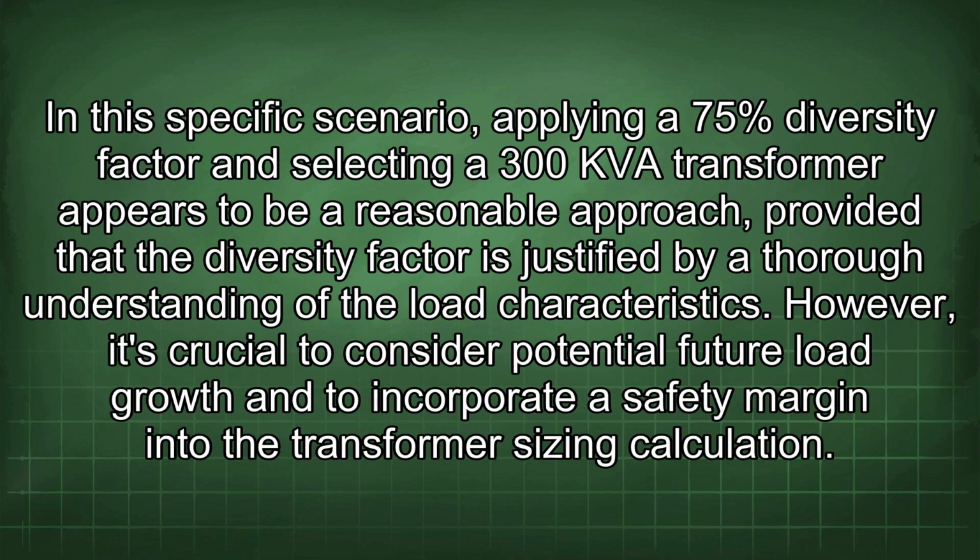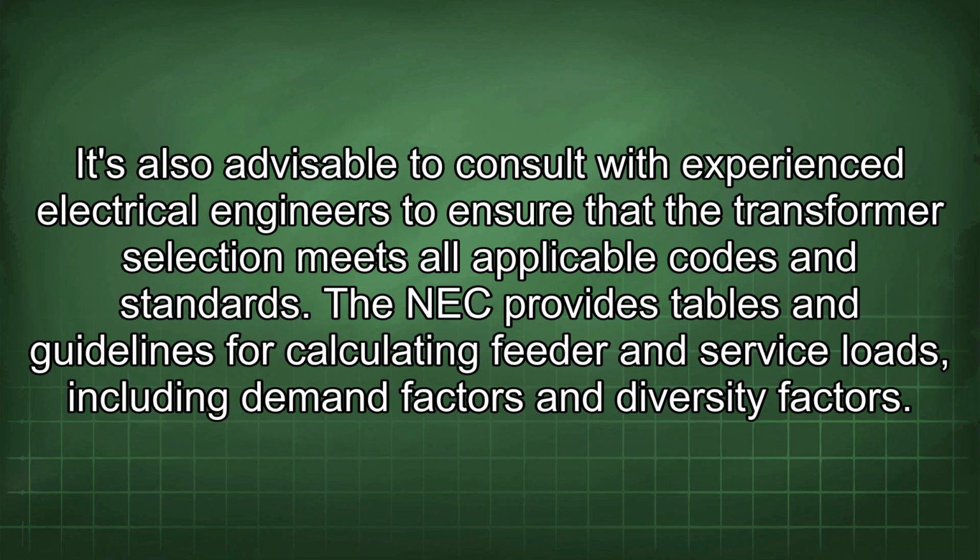In this specific scenario, applying a 75% diversity factor and selecting a 300 kVA transformer appears to be a reasonable approach, provided that the diversity factor is justified by a thorough understanding of the load characteristics. However, it's crucial to consider potential future load growth and to incorporate a safety margin into the transformer sizing calculation. It's also advisable to consult with experienced electrical engineers to ensure that the transformer selection meets all applicable codes and standards.